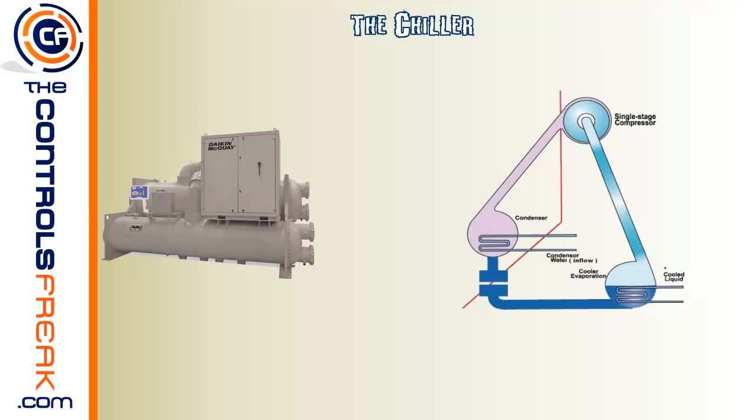One other thing to note about chillers is that in these barrels that you see here, there's many different bolts that come across here that seal up the 2 ends of this barrel. Inside the main portion of this barrel, these water lines that you see here are actually long tubes that run the full length of the barrels. So if you ever hear somebody saying they were changing out tubes or they have dead tubes in the barrels and so forth, these are many tubes, and there's many of them. I've seen some chiller barrels that had literally 100 or more inside the chiller barrel. So there's tiny little tubes all throughout this chiller barrel. And that's where you get the water running back and forth through this barrel to do the heat transfer.